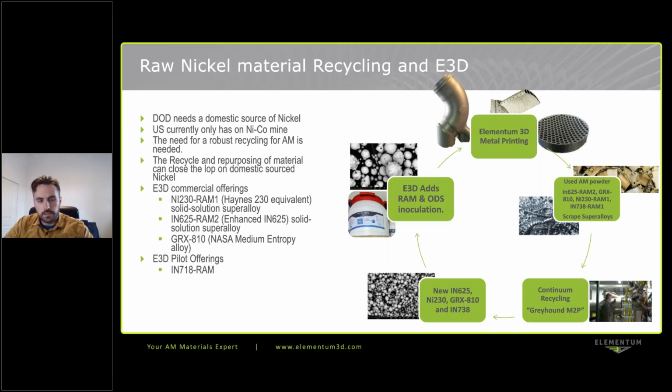And we've had great success in developing an alloy 230 equivalent, or Haynes 230 equivalent, and a 625 RAM2, which is a more enhanced 625, as well as partnering with NASA to commercialize and mix their GX810. And we currently have pilot projects trying to offer a 718 RAM product for industry as well.